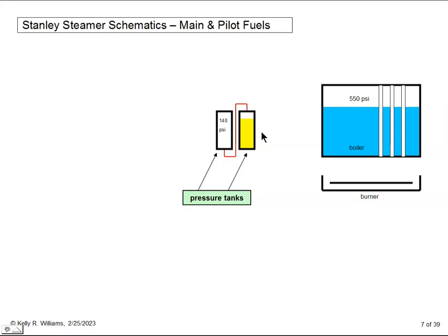Liquid fuel is also much more easily handled. It can run through small tubes, and it doesn't have to be physically thrown in a piece at a time while you're driving. And finally, using a liquid fuel allows us much better control of the fire. In a locomotive, there's no way to turn the fire off quickly, other than to dump all of the coal onto the ground. And obviously there wouldn't be a way to get the fire relit after that happened. For the frequent and fast demand changes of automotive use, the liquid fuel permits quick shut-off of the heat and a quick restart when we need it.